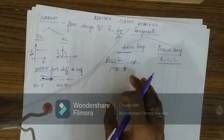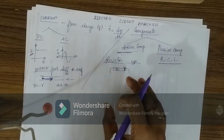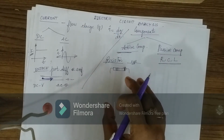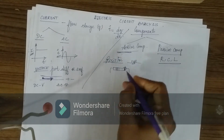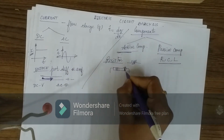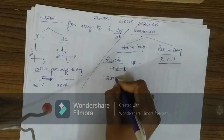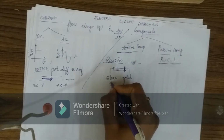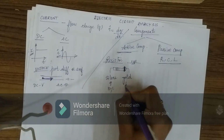So they give us what we call tolerance. We can expect the resistor to vary within a certain value. For this tolerance band, the color code will be silver, gold or no color. If it is silver, the tolerance value is 10%, and for gold, the tolerance value is 5%.